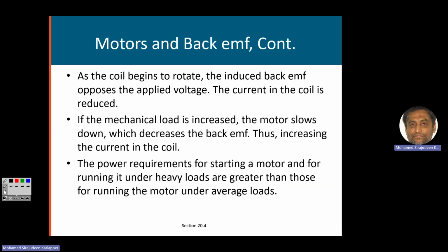If the motor is connected to a very heavy mechanical load, the motor will slow down because it is going to rotate something very heavy. This will decrease the back EMF. If the rotational speed is smaller, the flux change is smaller, and it will reduce the back EMF. This will increase the current in the coil.